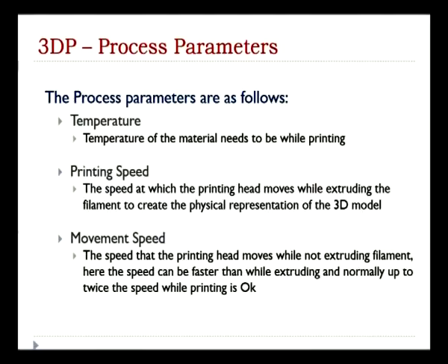Say, for example, I have a hollow structure in a particular area where I don't want to print any material. In that case, we consider the movement as normal movement. Generally, during delivery the speed is very idle or at a controllable level, particularly where we don't want to dispense a material but the delivery unit is simply moving. In that case, we prefer to go for higher speed, particularly twice or more than what we really want to print.